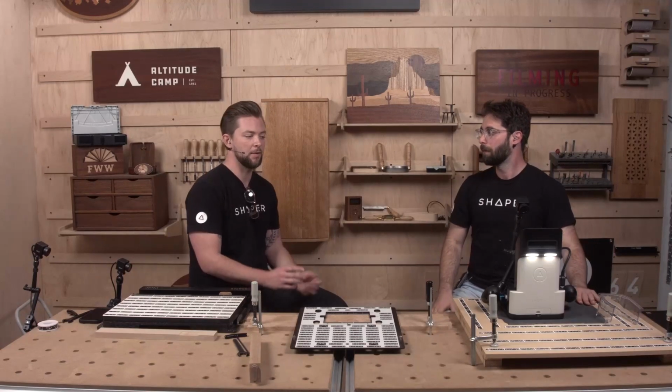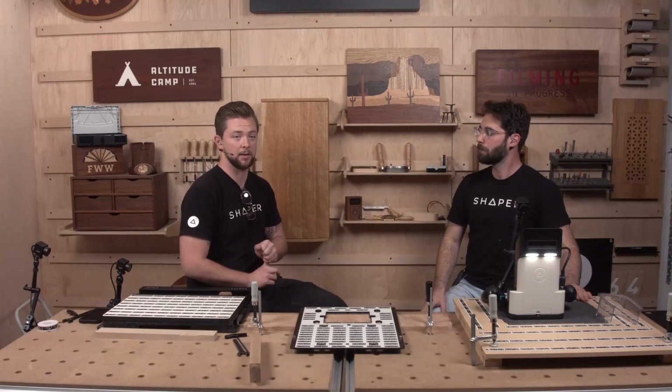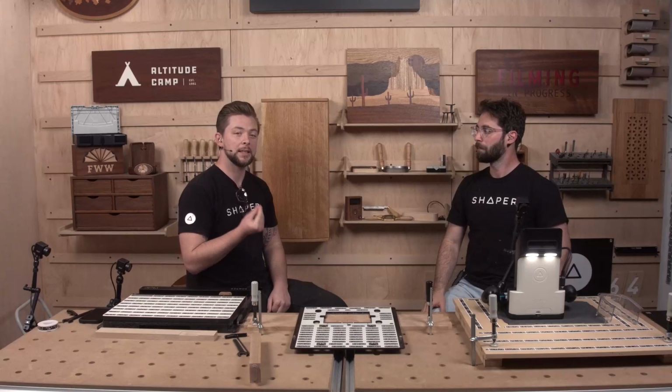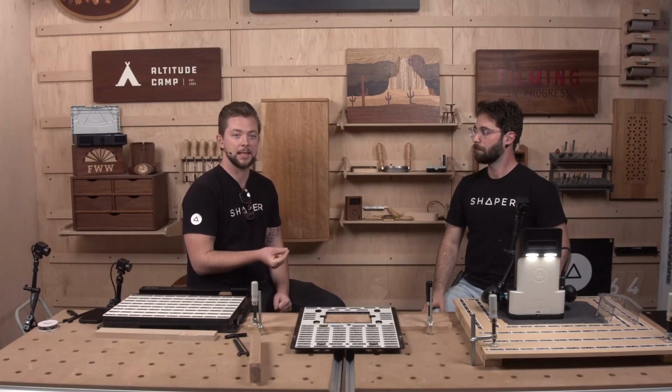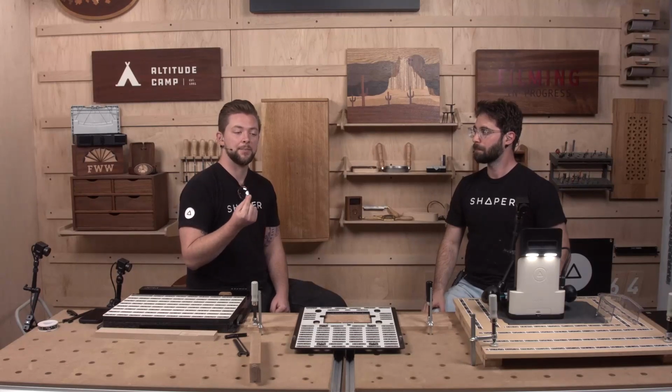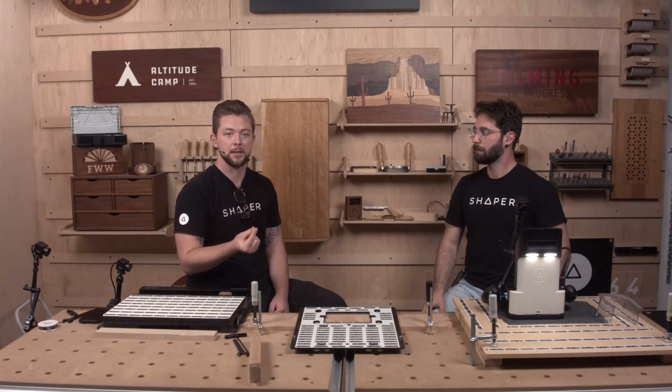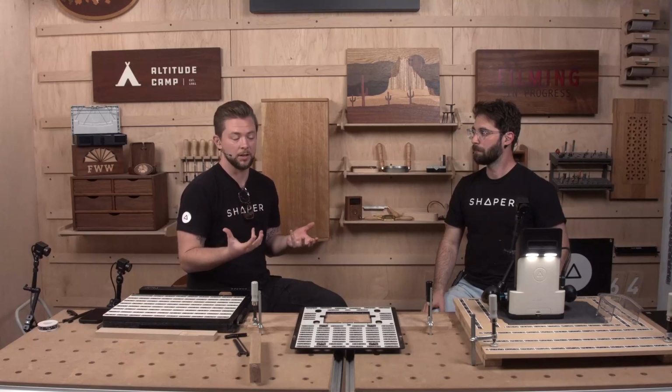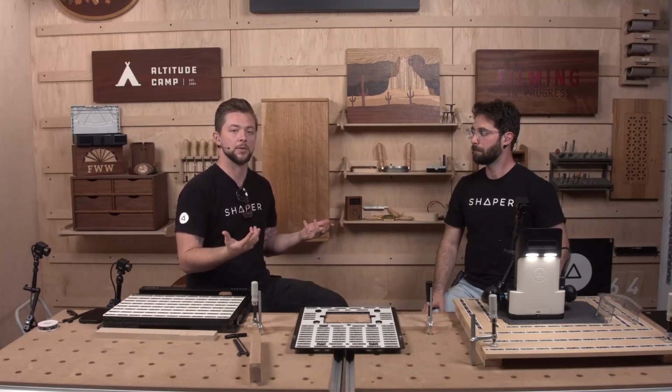Yep. So think if you're using sharp cutters like the standard engraving bit, or if you're doing really, really fine work, you got like a 32nd inch bit in there. You're doing fret work for guitars, something where maybe it's not the material, but it's actually the bit that you don't want to put the entire weight of Origin on top of. Perfect opportunity to use manual Z-Touch.